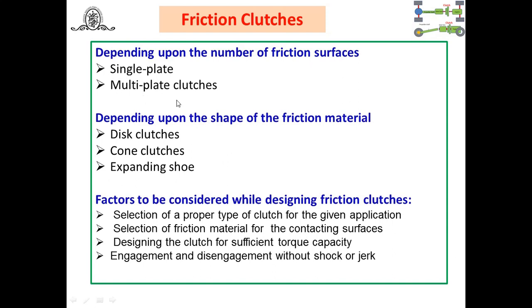That means when a single friction plate is used, you can say single plate, or when multiple plates are used, you can say multi plate clutches. Again, depending on the shape of the friction material, friction clutches are classified as disc clutches, cone clutches, and expanding shoe clutches. Again, how to select the clutch for our application?